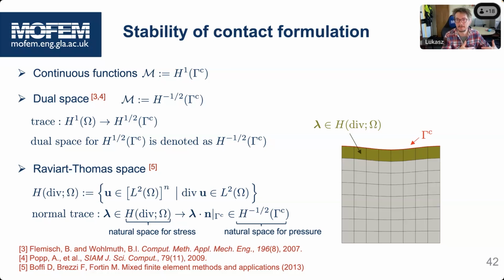So before we break the phase, thanks to the H-div space, we can calculate how much energy we release, so we can adjust the load such that we release the Griffith amount of energy per surface area.